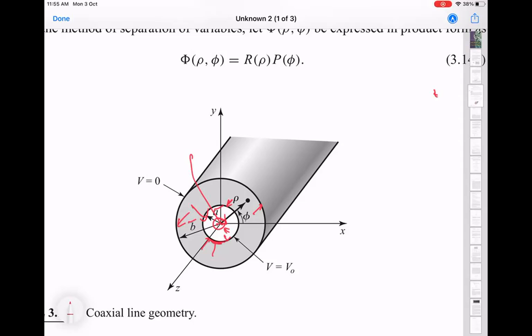There are transmission lines where there are no grounds, because all the models you saw till now actually do not distinguish between the two conductors, right? The telegrapher's models we saw, there's really no distinction; the ground is just a reference. You can equally define the ground on the other side, and it wouldn't really matter if you have drawn your model symmetrically. So remember, your model had L's and then C's to ground, right? This was not really considered as another metal.